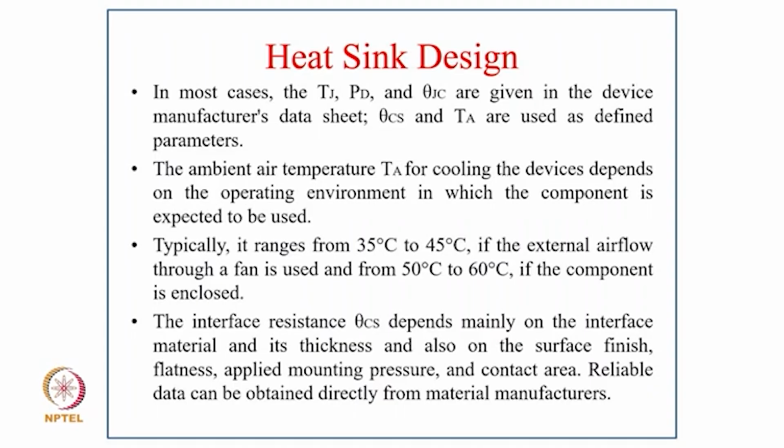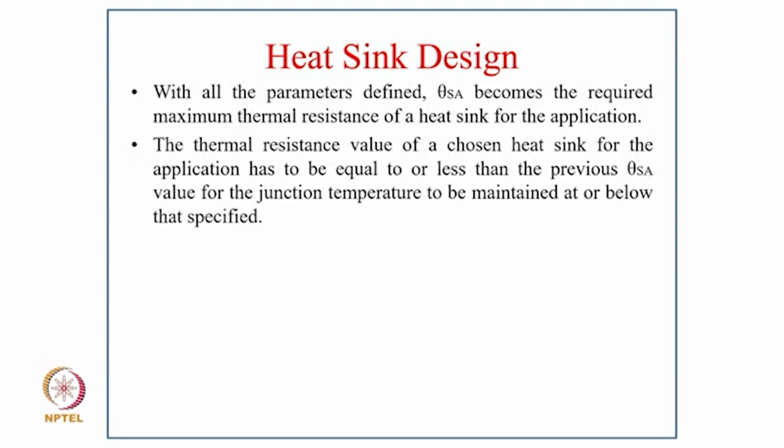The ambient air temperature Ta for cooling the device depends on the operating environment in which the component is expected to be used, and typically it ranges from 35 degrees Celsius to 45 degrees Celsius. If external airflow through a fan is used, or the component is enclosed, it ranges from 50 degrees Celsius to 60 degrees Celsius. The interface resistance theta Cs depends mainly on the interface material and its thickness, and also on the surface finish, flatness, applied mounting pressure, and contact area. Reliability data can be obtained directly from the material manufacturer.